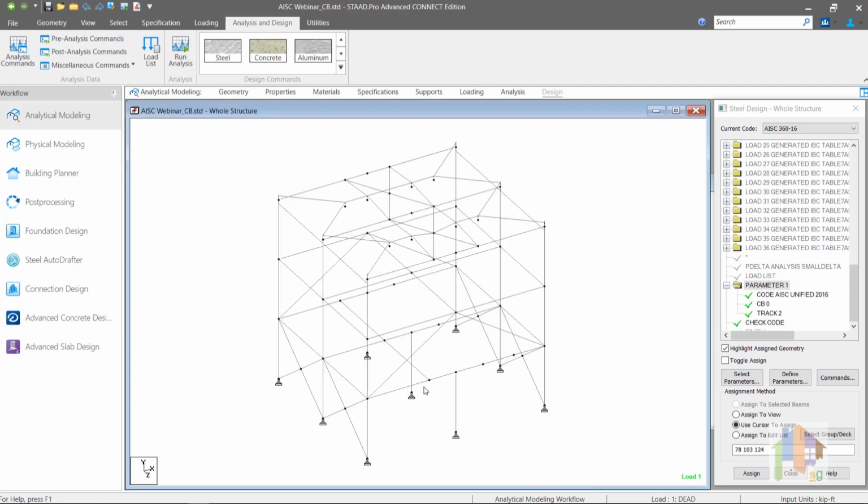For this case, the actual analytical member length is equal to the unbraced length, and if you specify CB as 0, the program calculates the CB factor based on the moment values for each member. And that is correct. Same for this member or this column. So if the member length is equal to the unbraced length, you can use CB value as 0. This produces more accurate results.